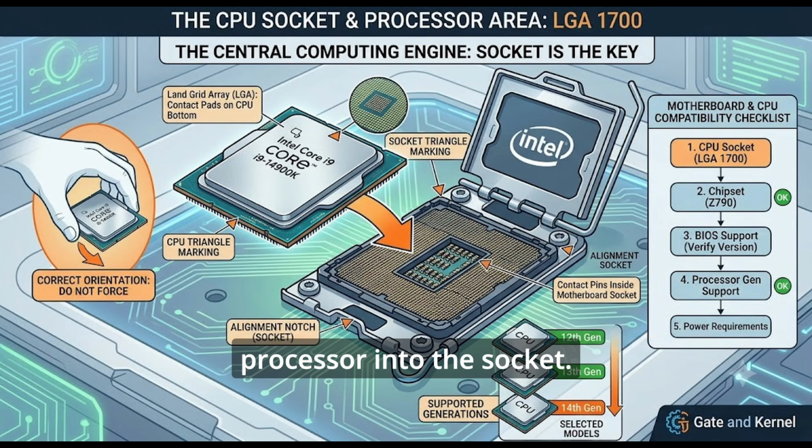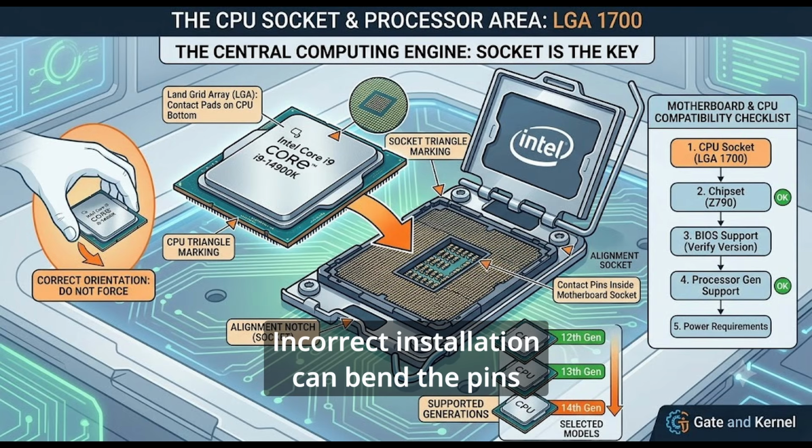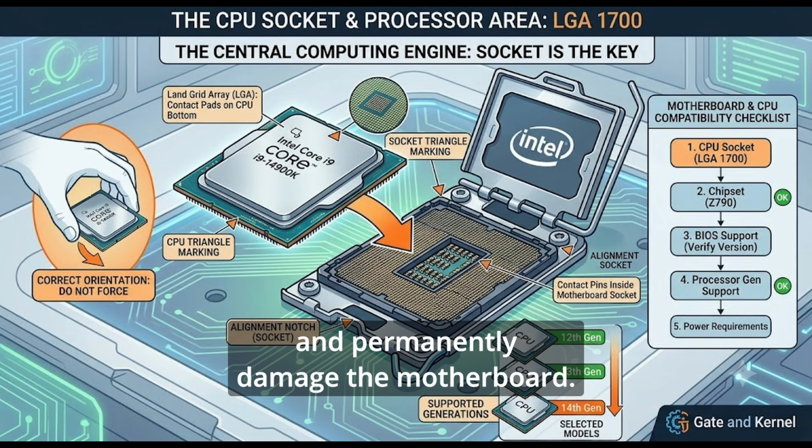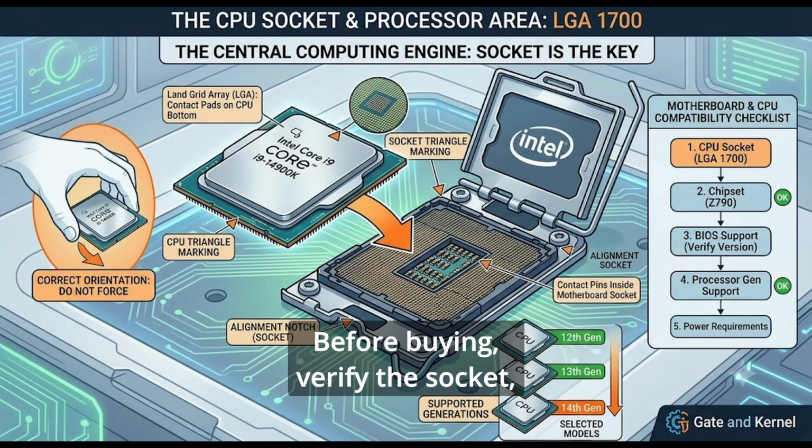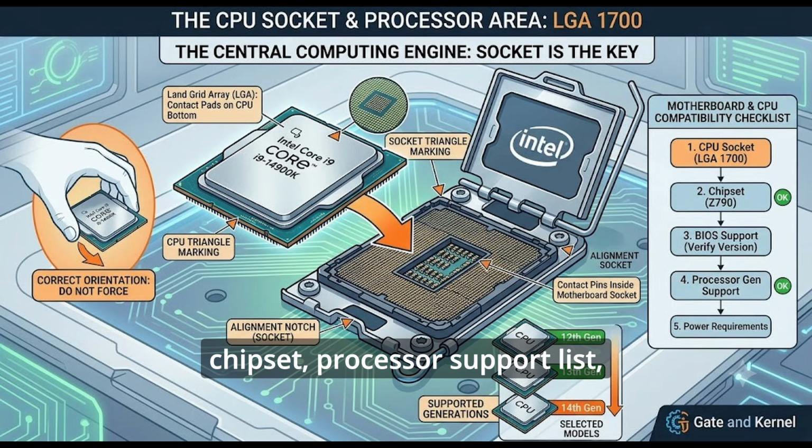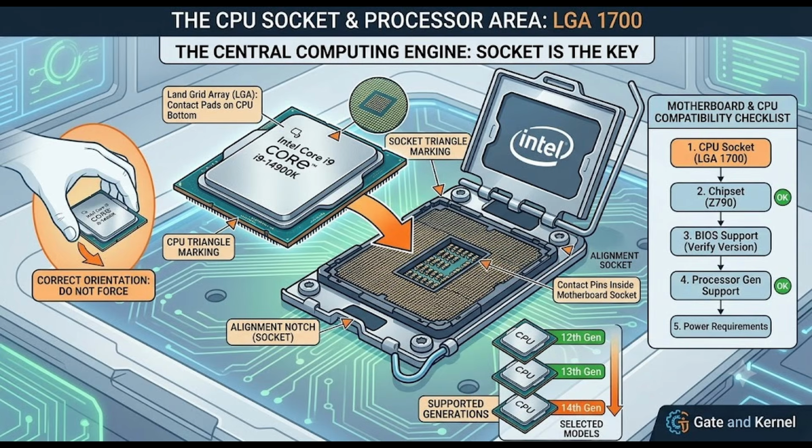Never force the processor into the socket. Incorrect installation can bend the pins and permanently damage the motherboard. Before buying, verify the socket, chipset, processor support list, required BIOS version, and power requirements.